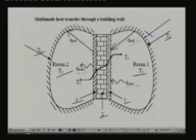Okay, because you have radiative heat transfer here, because the surface temperature of the wall is different from the surface temperature of the surroundings of room 2. So you have radiation. Similarly, this air temperature T2 is different from this surface temperature, so again you have convection. Okay, so this is a very typical example of multimode heat transfer, which we will be dealing with while doing air conditioning calculations.